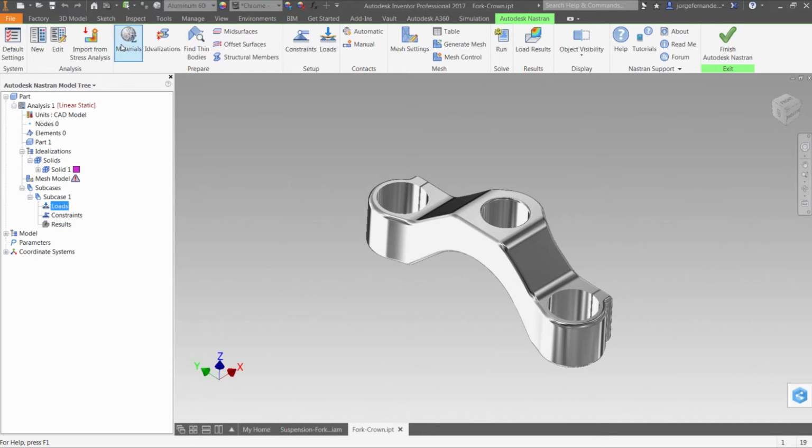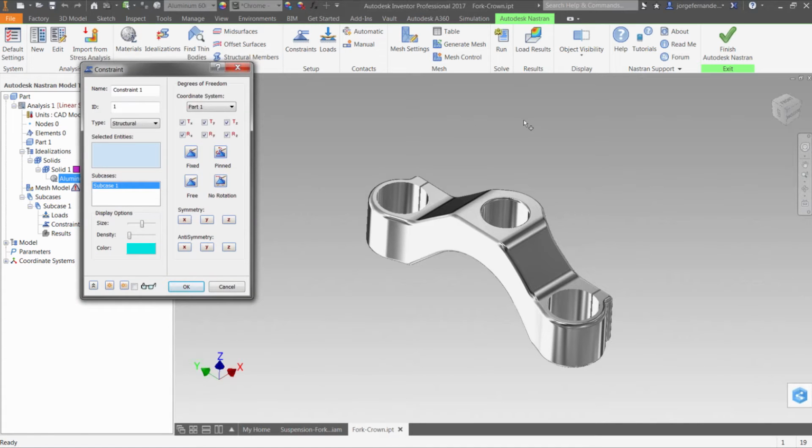Now that we've got this part running inside of Nastran In-CAD, one of the things we can start doing here is start to identify what type of materials we're going to use. We'll go over some of these and some of the other examples as well, but for now, we'll notice that there is actually aluminum in here already selected for me, so I can go ahead and move forward with this part. Now, it's a pretty straightforward interface, I like to think, where if you want to start adding the constraints as far as how this is going to be held down, we can very easily go to our constraints options here and be able to say that this is a fixed constraint. Notice there are other options in here where, if we knew that there was symmetry along this, we can actually do symmetry as well, which we'll utilize in just a bit.